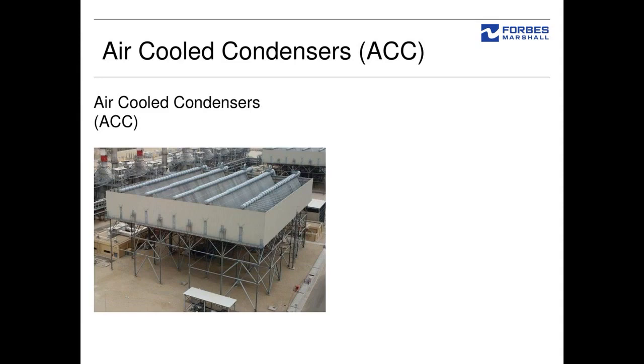Whenever sufficient cooling water is not available, people cannot use water-cooled condensers, and that's why nowadays air-cooled condensers have also become very popular, where steam is condensed using atmospheric air by putting large fans and large air-cooled condensers like shown in the photograph. In such cases, heat is directly rejected to the atmosphere without using cooling media like cooling water.